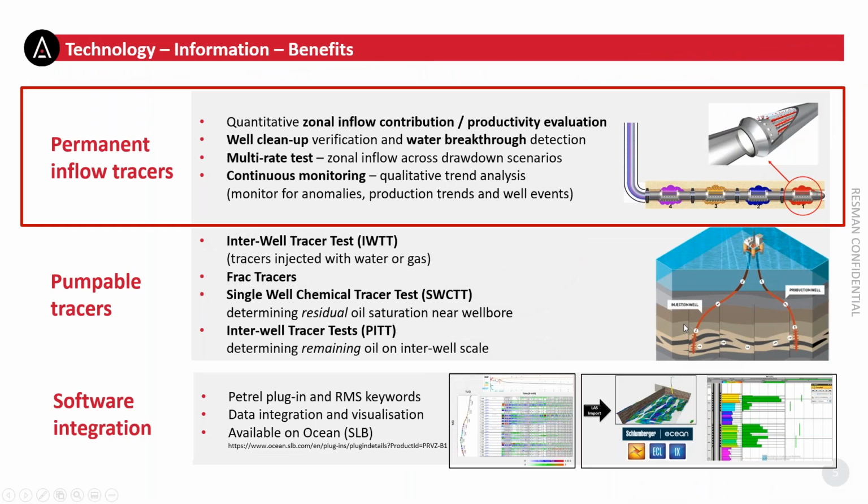Thank you very much, Asel. Hi, everyone. It's very good to have you around. So I will today explain to you the technology that we have, the Inflow technology. That is one of the multiple technologies that Resman do provide. So we've got the first one, the Inflow technology, and we've got the pumpable tracers. The pumpable tracers has been explained before in one of the previous webinars, and it's mainly about injecting tracers, while the inflow tracers are the ones which we would install permanently into the well, and that will help us to understand about well cleanup, about the productivity of the zones and the qualitative inflow from each of the monitored zones.